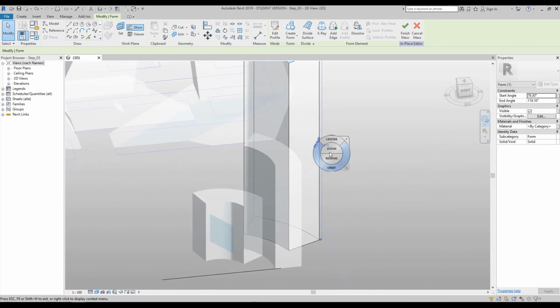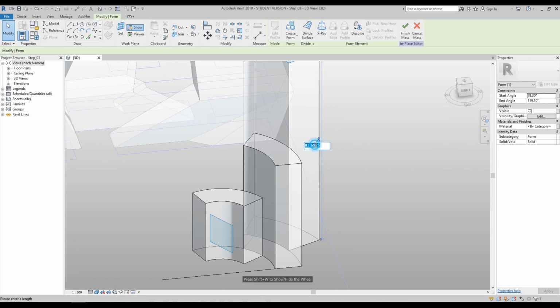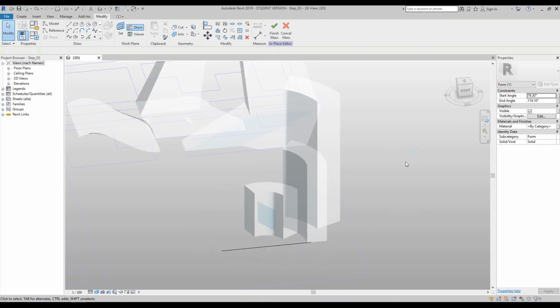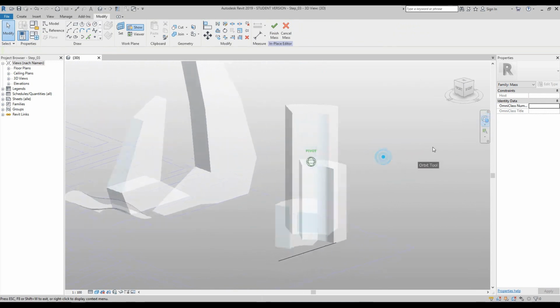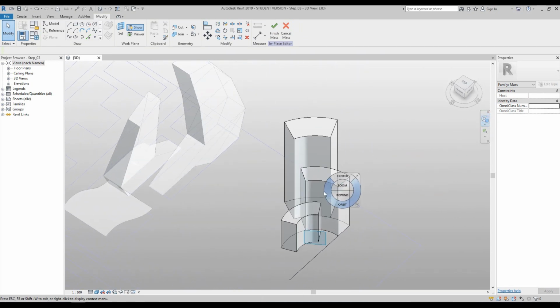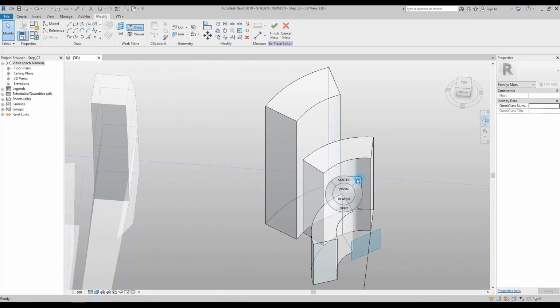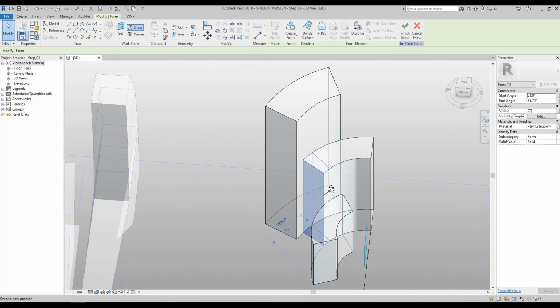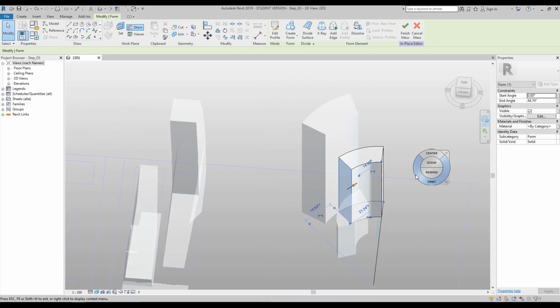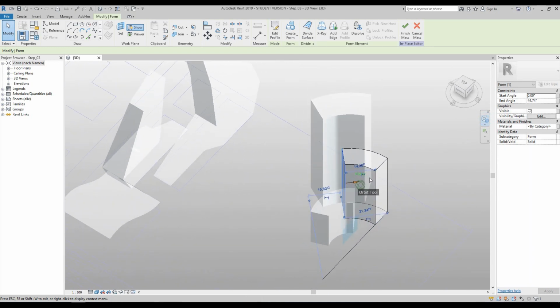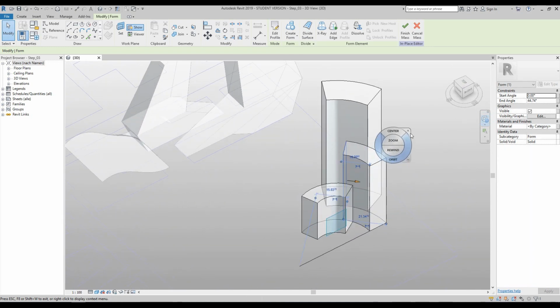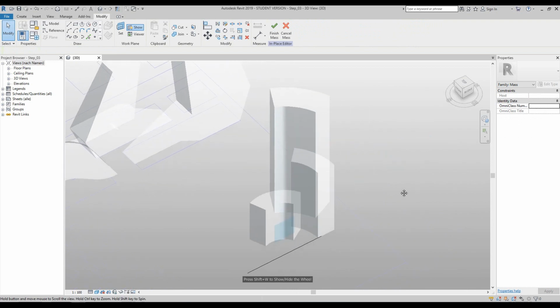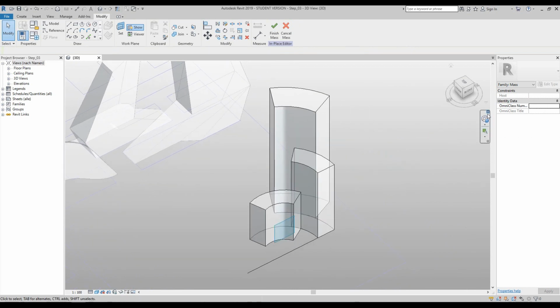And you know what, we can make the temporary dimensions, let's make it 75. So it's about there. You know what, I think this needs to move a little bit, so we'll select that and pull it slightly in. Yeah, that's better. Okay, so once you've got to this, press the negative space, so nothing's selected.